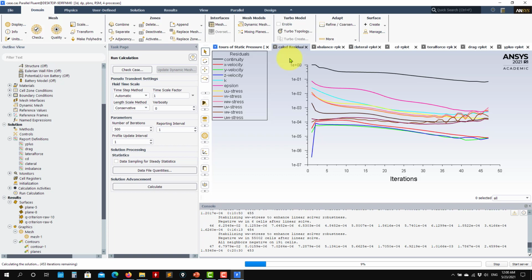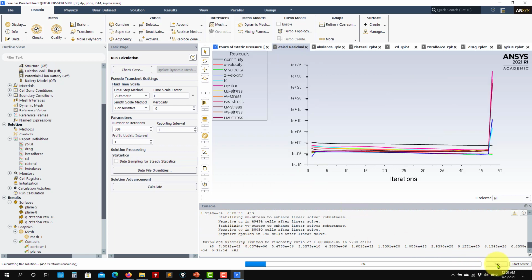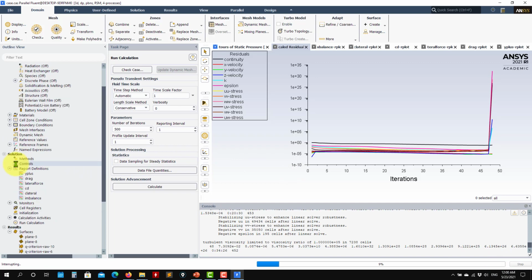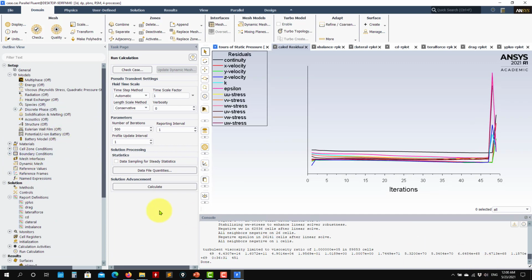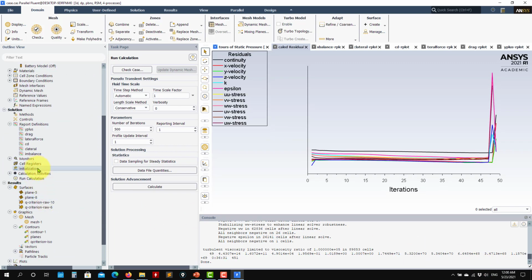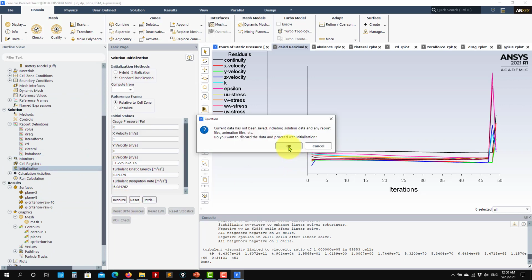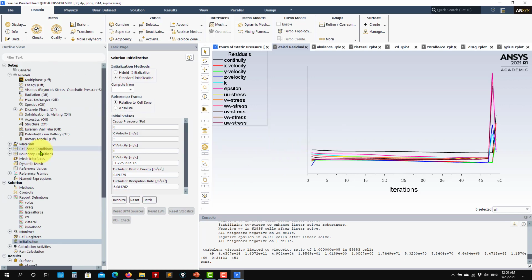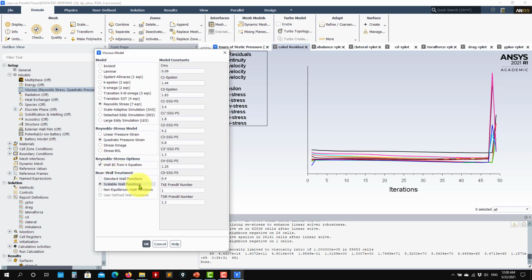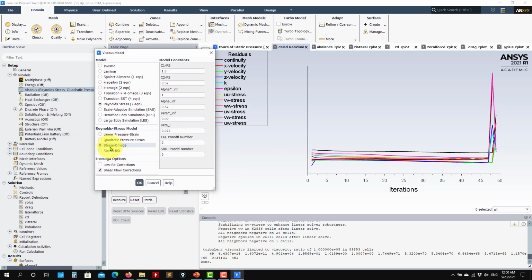Okay, so the solver is running and see it is giving this funny message telling you that you have negative values, and now it's diverging. So you see that this one is still diverging. It's not very easy to make converge. I would like to have one of these converging. So let me initialize again and let's use this one; usually this one and this one also work relatively well.